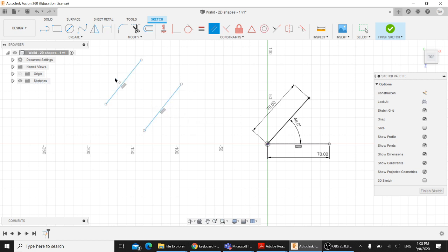Then they will have the same slope as you can see here. But if I want to make my two lines have this slope, I will go to parallel, choose this line as my first line, click on it, and just click on the other line. So again I have two parallel lines. However I change its location, it will still be, of course, parallel.